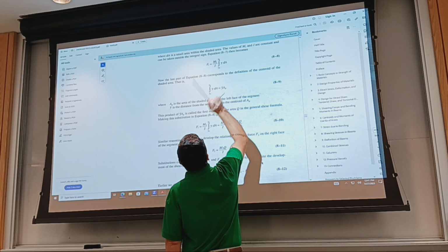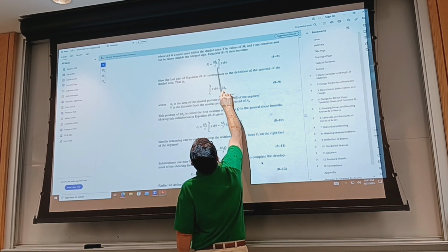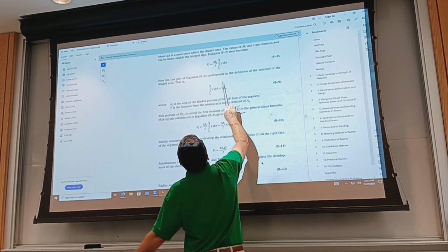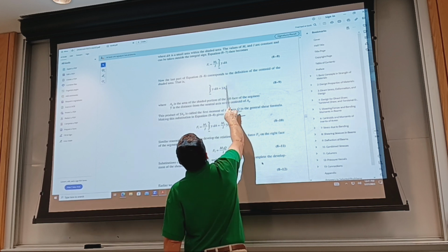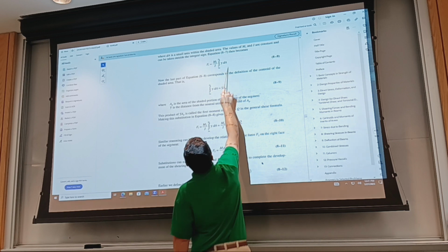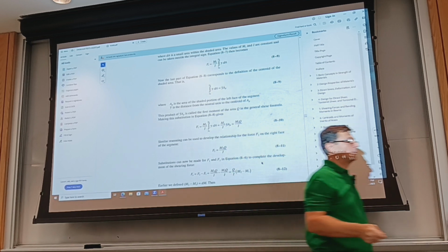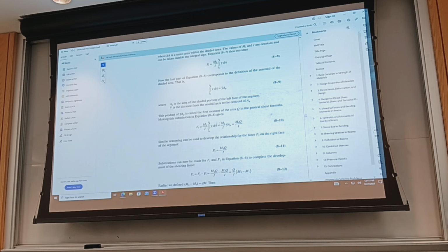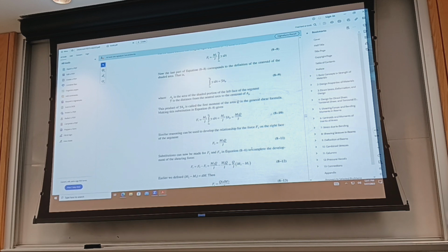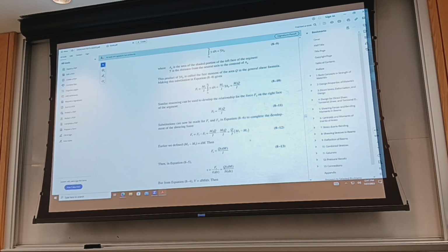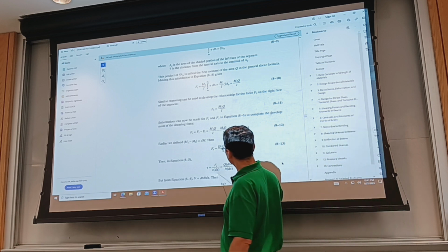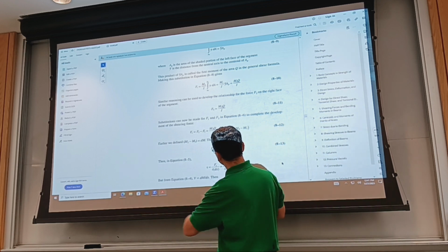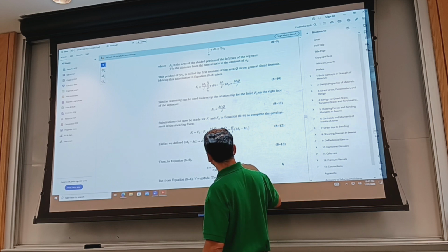So where were we? We have some constant, the moment of inertia, and the moment to the left section, and this is what? This is the integral of the centroid of the partial area times the partial area. Okay, all right. So moving forward, I said that shear stress is going to be shear force divided by the horizontal section area, right?